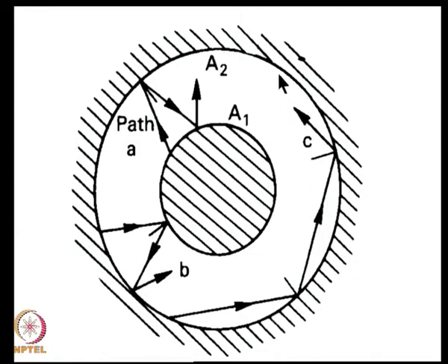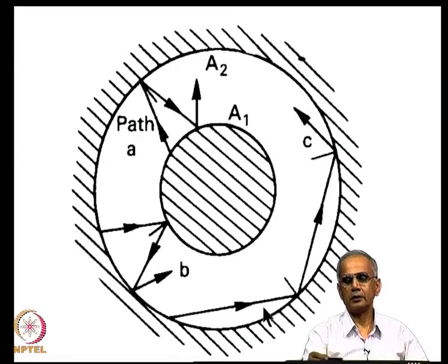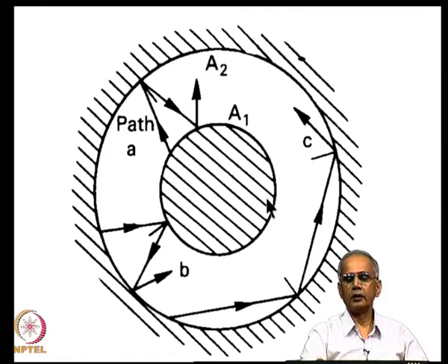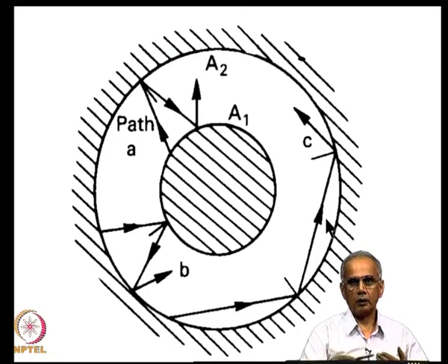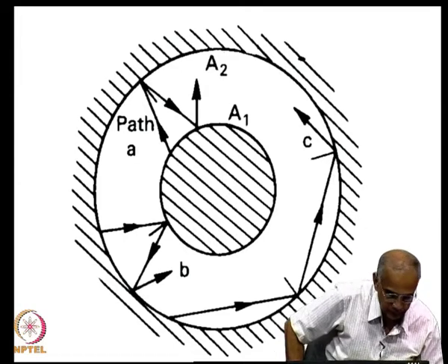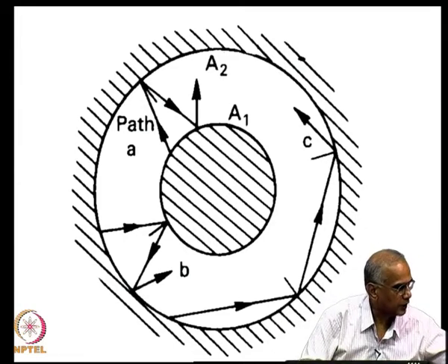The radiation that is emitted in this quadrant only will bounce back between 1 and 2, only radiation coming out in the other direction will go. Even from here, this is the normal emission, this is the tangent, even tangent emission from 1 will come back to 1, will not go to 2. Once you have realized this, you can write down the final expression.